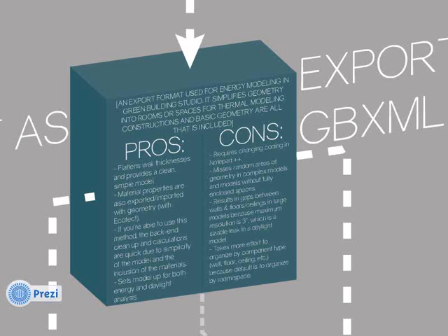Also, the simplification is really worried about interior volumes, so sometimes you'll get gap interpolations between those different zones or spaces or rooms. That always has to be taken into account if you're trying to do perspective renderings or visualization analysis. That level of simplification might not be appropriate for that, but it might be fine for doing LEED daylight analysis and stuff like that, right?